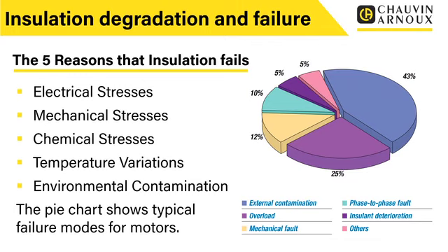Mechanical stresses. Mechanical stresses are to do with starting up and shutting down. That could put torsional stress and things like that within the windings and within the insulation. Also, balancing issues can cause a lot of mechanical stresses. You can imagine that if it's vibrating or if the thing's not aligned correctly, these again can cause mechanical stresses on the insulation. Chemical stresses, again, come in many forms, but this could be the proximity of chemicals, oils, or maybe even corrosive vapors, dust. All of these things can deteriorate insulation.